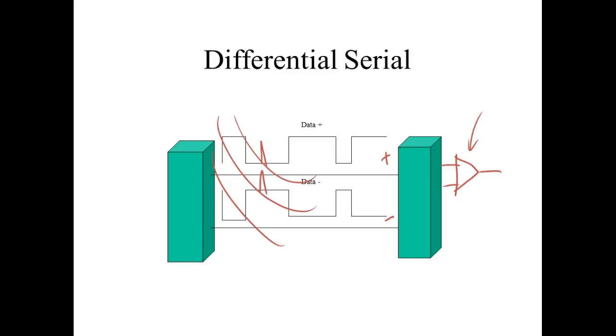Differential. Serial ATA uses differential. Ethernet uses differential. USB uses differential. And this is basically serial ATA. So what they did is they can run extremely fast speeds because now the wires won't interfere with each other. So we went from parallel ATA on our mass storage devices over to serial ATA. Now our hard drives are all serial ATA, which instead of having this big old flat cable, which is about that big, we got a little old tiny flat cable. We can route them. It makes airflow inside our computers so much easier. And it's revolutionized serial communication.